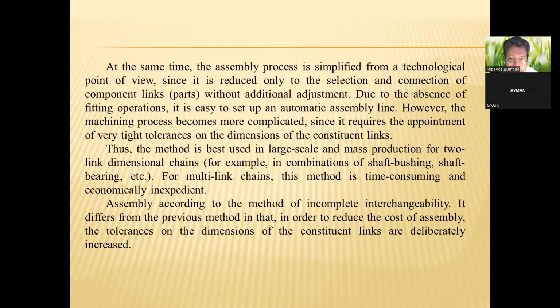Assembly according to the method of incomplete interchangeability differs from the previous method in that, in order to reduce the cost of assembly, the tolerances on the dimensions of the constituent links are deliberately increased.